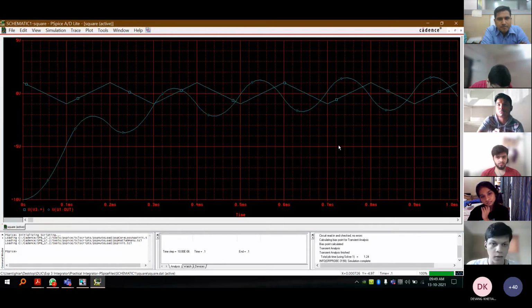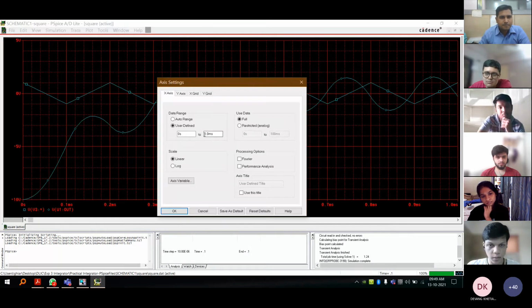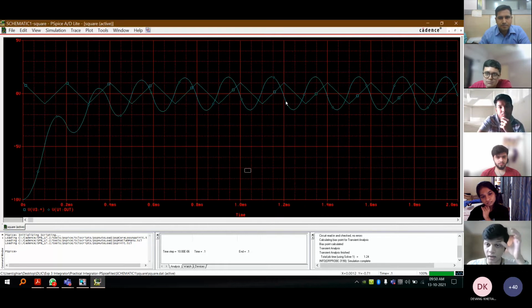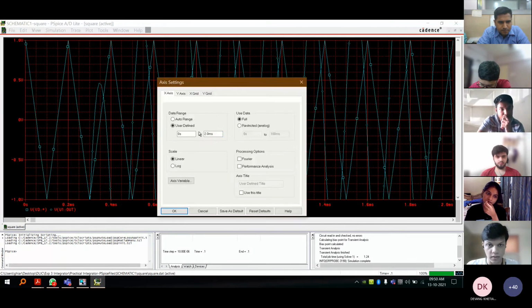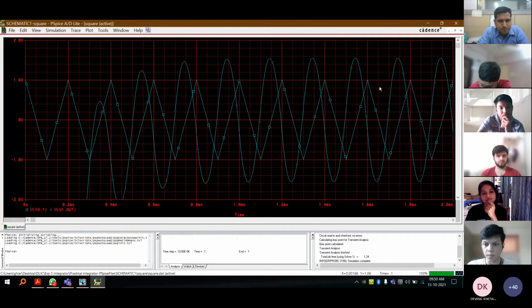The benefits of a practical integrator. And you can see that again here, the capacitor is taking some time to charge up. But once it does, you get a pretty good waveform about your integrator. Yeah, there we go. And again, you can modify this a little. Let's say we just make this 1 volt to -1 volt. Sorry. Okay, that is disgusting. Sorry, I'll just make this 2 volts. I'll make this a much better waveform you can see because the charging of the capacitor can be a little annoying to deal with. But here we go. We have our almost perfect triangular waveform and we have our sinusoidal waveform.